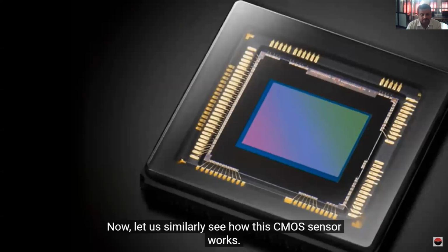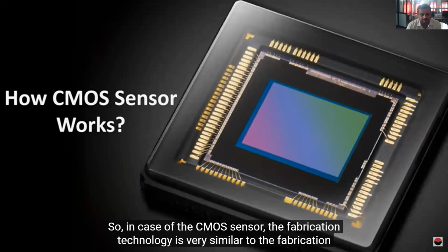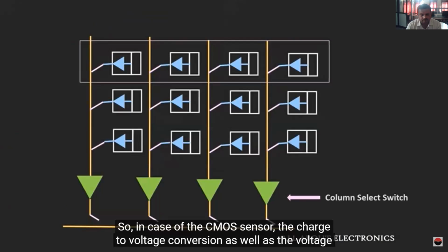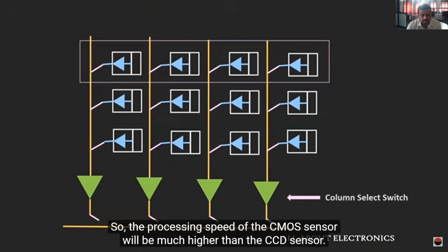Now let us similarly see how the CMOS sensor works. In the case of the CMOS sensor, the fabrication technology is very similar to the fabrication technology of the integrated circuits. Because of that, many peripheral circuits can be integrated inside a single chip. In the case of the CMOS sensor, the charge to voltage conversion as well as the voltage amplification is carried out in the pixel itself. And as the charge to voltage conversion and the amplification is carried out in the pixel itself, the processing speed of the CMOS sensor will be much higher than the CCD sensors.